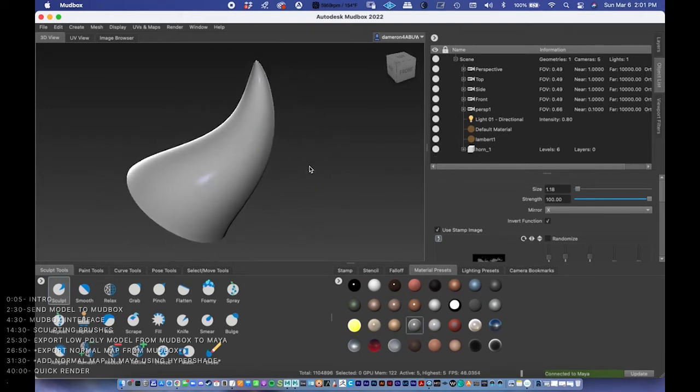And so now let's start sculpting on this thing. So to sculpt, I'm going to show you the sculpt, the smooth, and the wax sculpting tools here. So sculpt, I double click it here. The strength is at 100, which is why when I pressed it went kind of crazy in there. So we're going to want to bring this, the slider might delay a little bit on you. Let's bring it all the way down to 3. We're working pretty small here, so this might need to be at like 1. Let's try sculpting here.